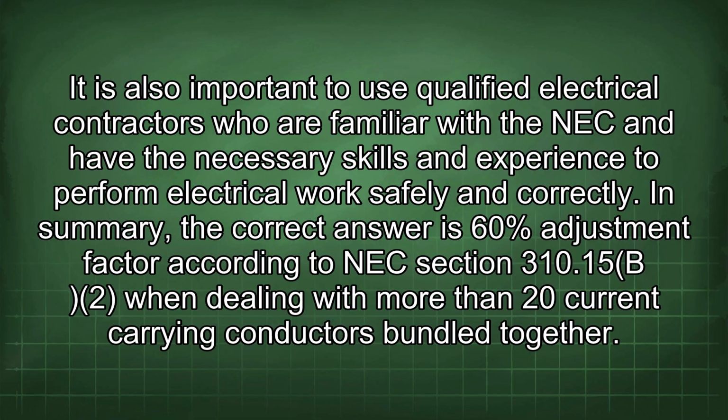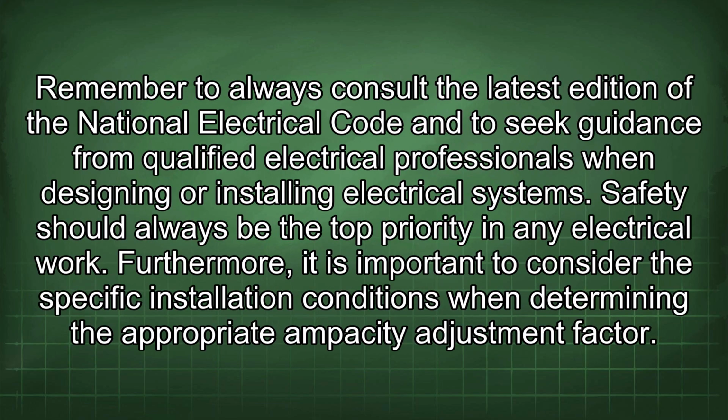In summary, the correct answer is 60% adjustment factor according to NEC section 310.15(B)(2) when dealing with more than 20 current-carrying conductors bundled together. Remember to always consult the latest edition of the National Electrical Code and to seek guidance from qualified electrical professionals when designing or installing electrical systems. Safety should always be the top priority in any electrical work.